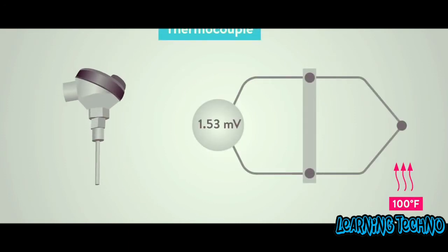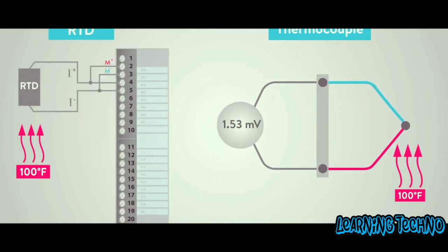A thermocouple, or simply TC, is comprised of a couple of specific dissimilar wires joined together, forming the sensing point or junction. Based on physical characteristics called thermoelectric effect, when this junction is placed at different temperatures, different millivolt signals are generated, which can be interpreted as an indication of the temperature. In comparison with RTDs, thermocouples are self-powered and require no external excitation current source. Thermocouples are commonly used for furnaces, gas turbine combustion chambers, high-temperature exhaust ducts, etc.